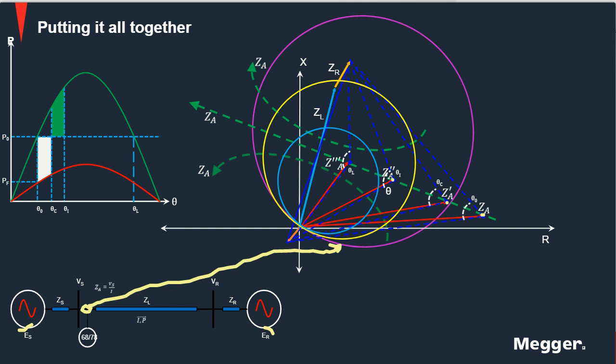But as the power oscillates, and remember, we are not talking about an actual fault in the system, we're talking about an oscillation that's typically a slow movement of the voltages and the currents, the impedance is going to go, and it can get into the characteristic of the relay, making it trip.